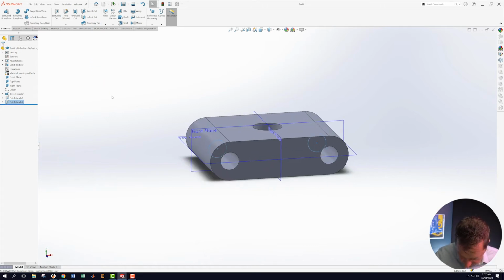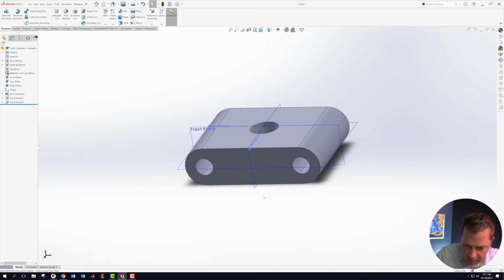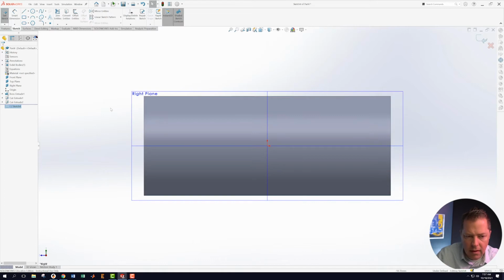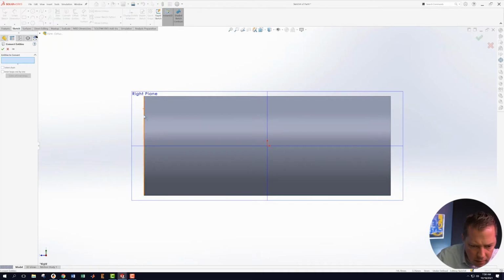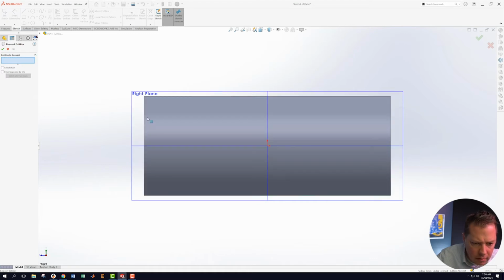That has got me most of the main features minus all of the fillets, which I'm going to do last. And actually, of course, I've got to do that very funny looking thing. Okay, so section AA has a cross section on it. So this is section AA right here. Let's go sketch on that. Okay. So now we need to make a cut. Okay, so let's do some convert entities here for a second. Let's convert this thing. And not that thing. Clear. Let's go get that. Okay.